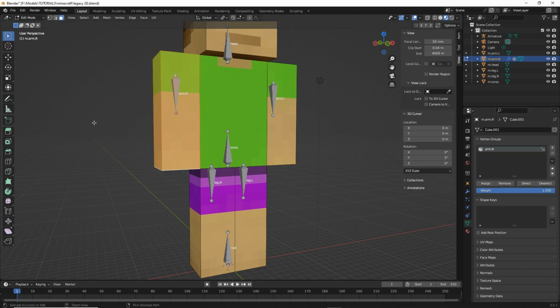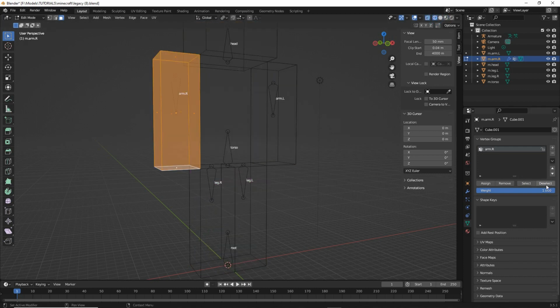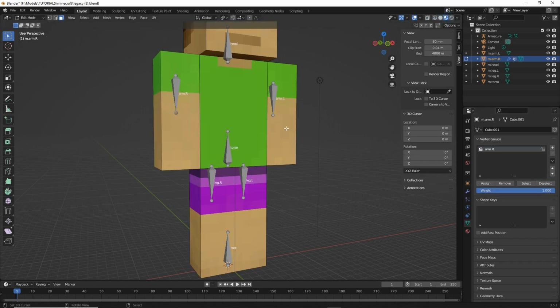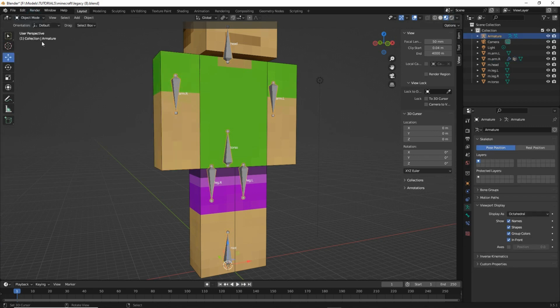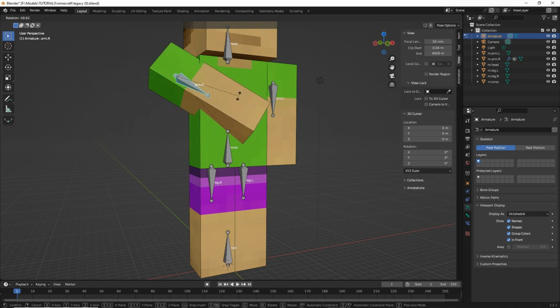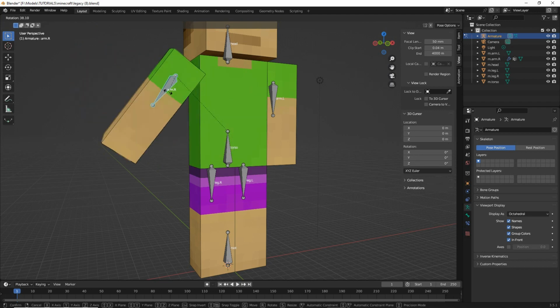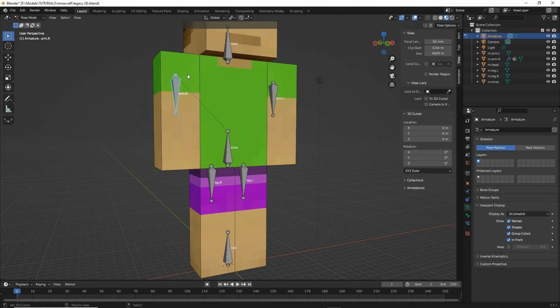And we should find that our mesh, the entire object, let's just go into wireframe for the moment, is selected. And what we'll find, if we switch back to object mode, select the armature, pose mode, if we now move that bone, the arm moves with it. So it's a twofold process. The armature modifier signifies the link between the two objects.